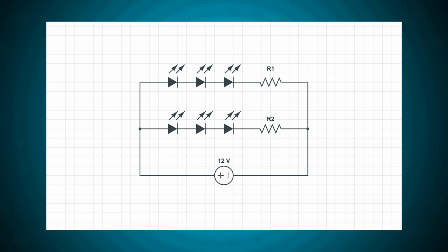The resistor here is placed at the negative terminal, and I guess it's obvious it can be placed at any part of the circuit as long as it is a serial connection. Why do we need 2 resistors? In theory, we could use this connection scheme and end up with a single resistor. Problem is, LEDs, just like regular diodes, have the so-called parameter spread, which means no two parts are the same.